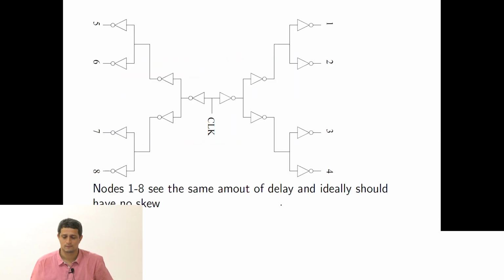The clock generation happens at a central point in the chip, because the clock has to be insensitive to temperature, voltage changes and all that. So you make a PLL based clock or something like that, which is very stable and has no jitter. What is jitter? Basically the clock edge just moves around a little bit randomly. With time, one edge can go this way or that way. So you want to design something with lower jitter, and then you distribute this clock through the entire chip in a tree-like fashion.